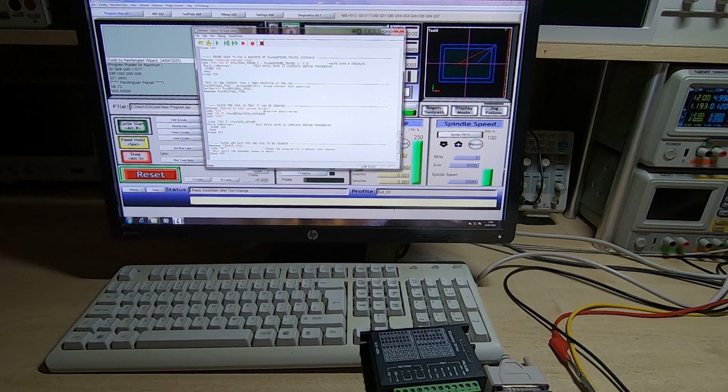It says F10 here, but in the machine that you'll see running in the workshop, this is an actual variable. This is just for testing in the lab. So it probes down to the tool tip, touches the zero pad, at which point the probe input will be triggered.